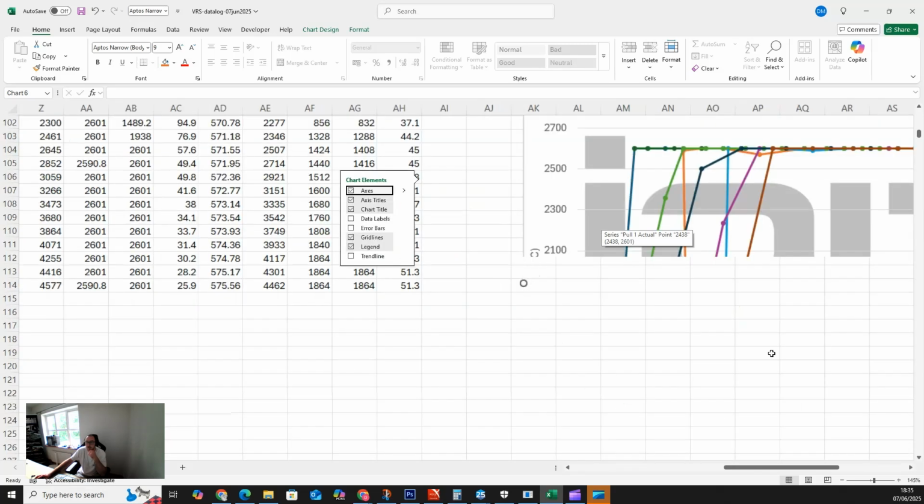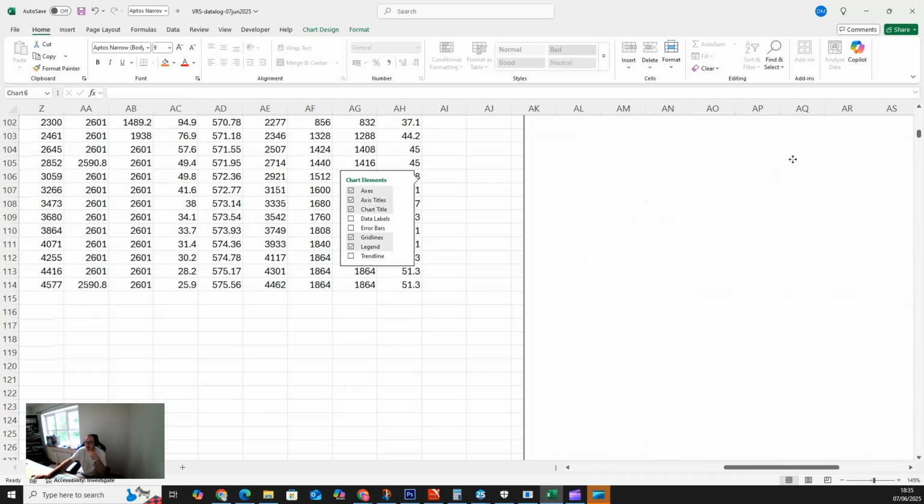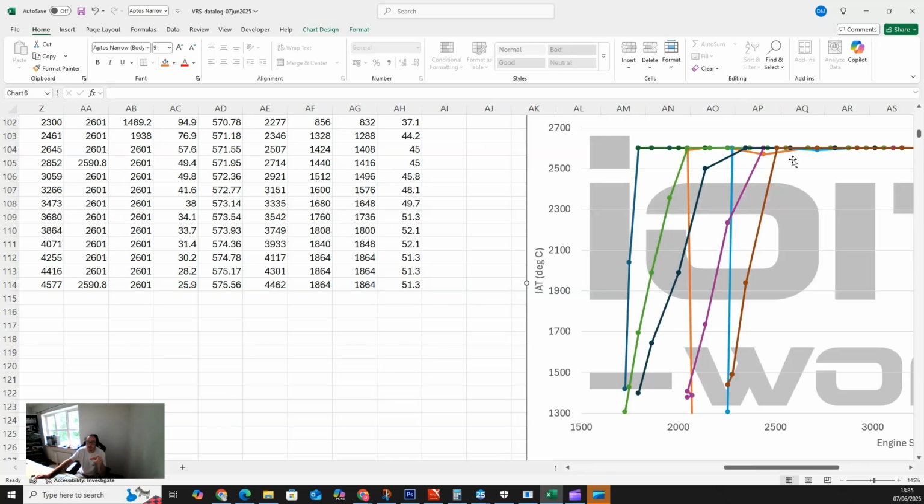Okay, so I'll talk here while it's refreshing itself, but I would say, and again, this is an experience thing, I'm not seeing massive undershoot in the data here, which would indicate to me there isn't massive overshoot either. You will see, and I've seen this before in the past, tuning hybrids. Now, I suppose it's a long time since I tuned a hybrid, and I'd imagine they're probably better set up now with improvements in technology and the machines used to calibrate the variable geometry turbines.